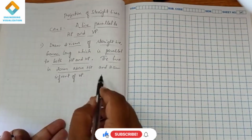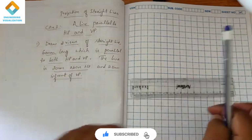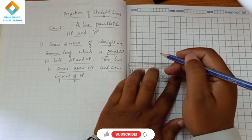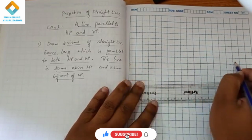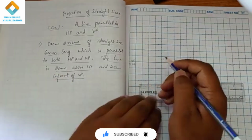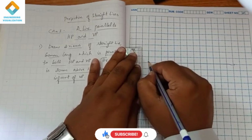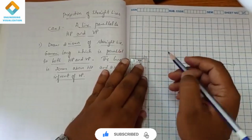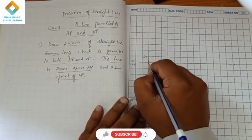The line is 20 mm above HP and 25 mm in front of VP. Here we are going to use only the first quadrant. First I am going to draw an XY line, with VP and HP and the first quadrant. The line is 20 mm above HP, and above HP means it is our front view, so here vertically I am marking 20. It is 25 mm in front of VP, and in front of VP means it is our top view, so it is 25.